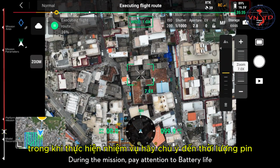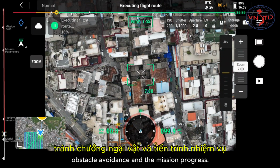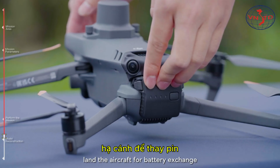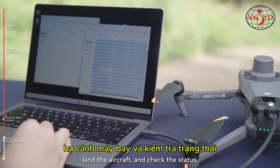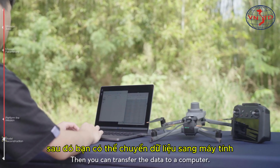During the mission, pay attention to battery life, RTK status, image exposure, micro SD card storage, obstacle avoidance, and the mission progress. If the mission couldn't be finished in one sortie, you can pause the mission, land the aircraft for battery exchange, and resume the mission. After the mission is finished, land the aircraft and check the status. Then you can transfer the data to a computer.